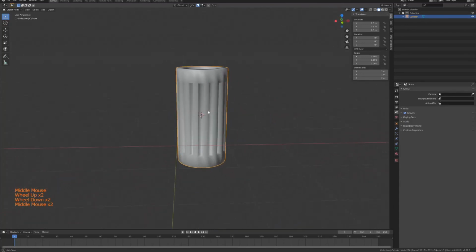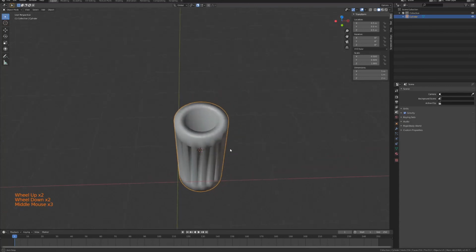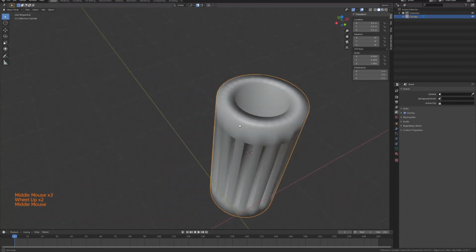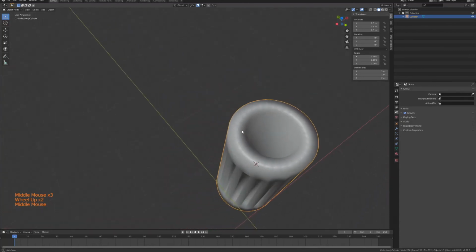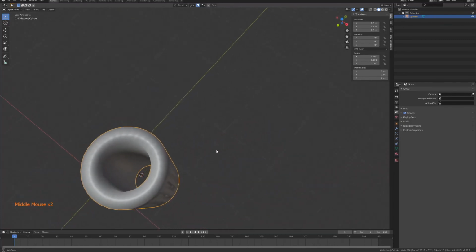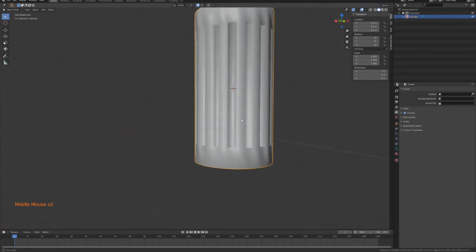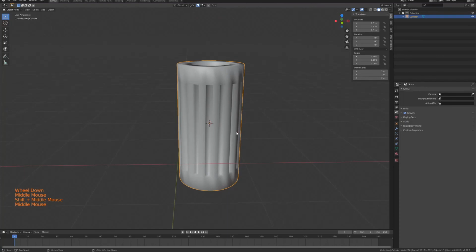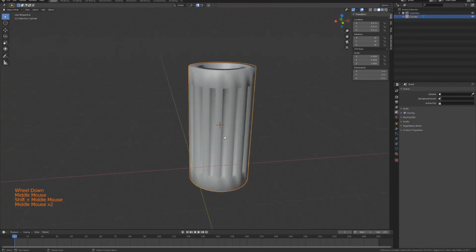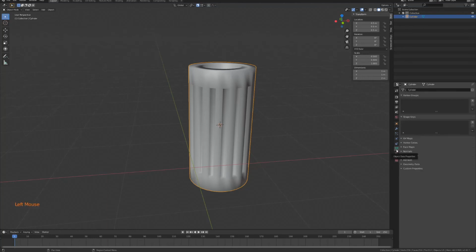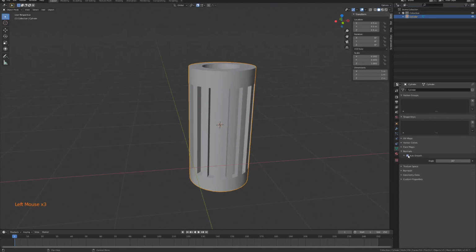So right now, you can see a bunch of little artifacts from all the shading, and it just looks generally pretty bad. So what you do is, first of all, you keep it like this. Next, you go over here into the object data properties. It looks like this green triangle here. You click on that, you open up the normals tab, and you enable auto smooth. Blammo.